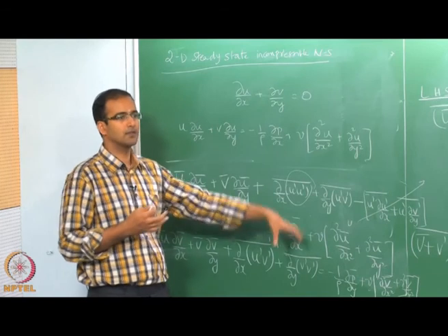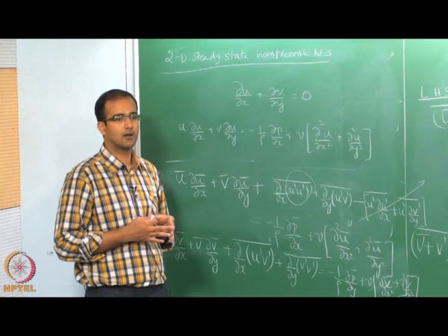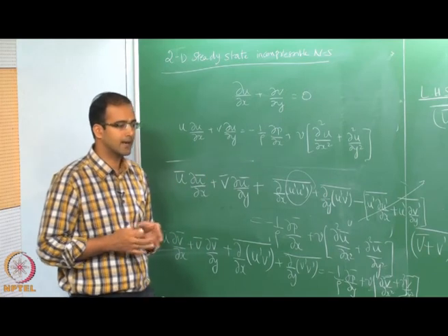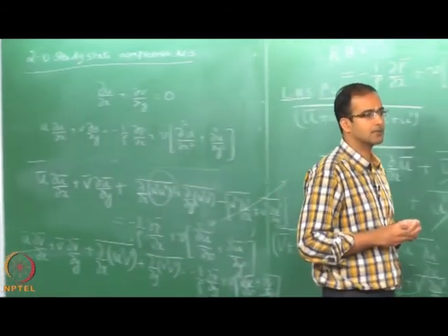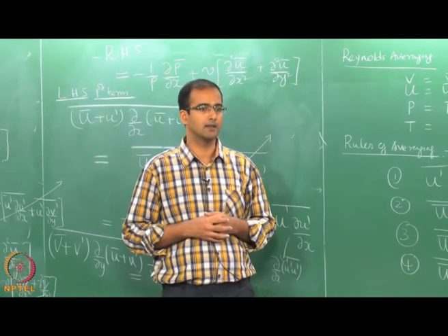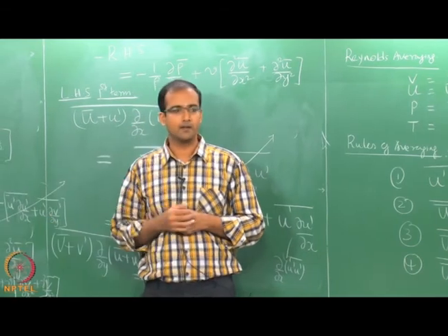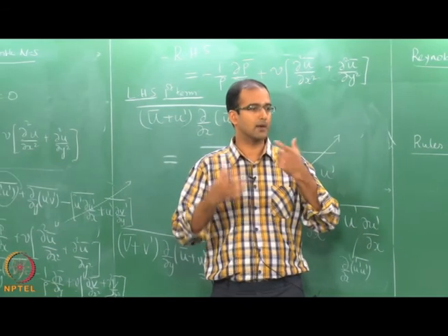They are grouped along with the viscous stresses and called together the total stress. So, it seems that there is an additional stress coming in turbulence, but it originates from the inertial terms, and that is why when they are taken to the other side they are given a negative sign.